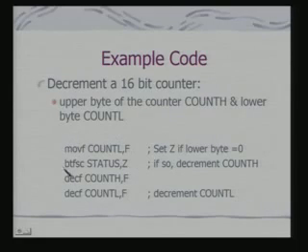Now the interesting feature is, if an interrupt occurs while this code is in execution, what can happen? Try to understand this. Your decrement may not take place correctly, because your counter is not getting decremented by an atomic operation. Is this clear? Because there are 2 bytes and they have to be decremented. So if you want to ensure an atomic decrement operation on this counter, you need to protect this code. That means you need to disable the interrupt from occurring.